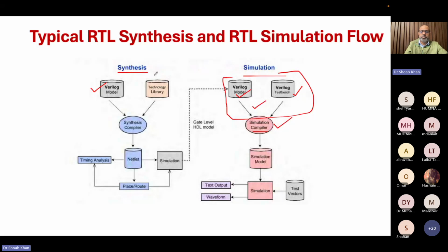And once you're doing synthesis, you go to a fab and ask them to give you a technology library. Technology library means what kind of transistor they are using. You must have heard about 6 nanometer versus 7 nanometer versus 9 nanometer versus 30 nanometers. And there are different fabs in the world. It's like once you're compiling a code, you mention whether you are compiling it for an ARM processor or MIPS processor or Intel processor or a digital signal processor, because this high level C or C++ code has to be converted into the assembly language of the processor, the instructions it supports.